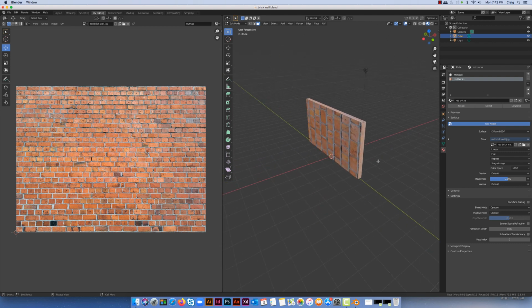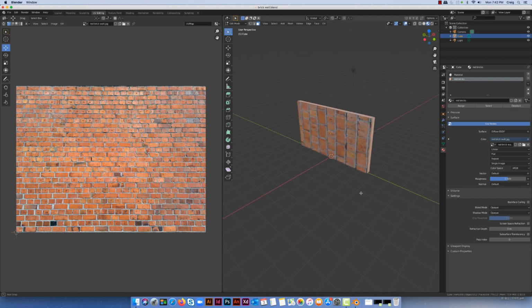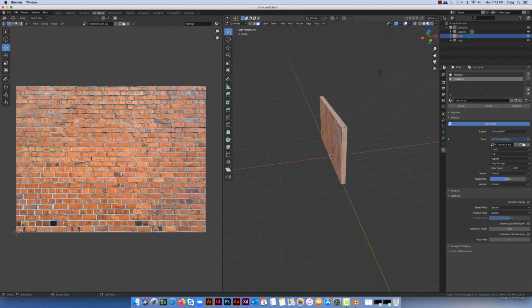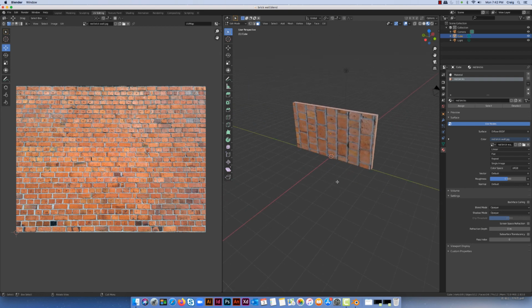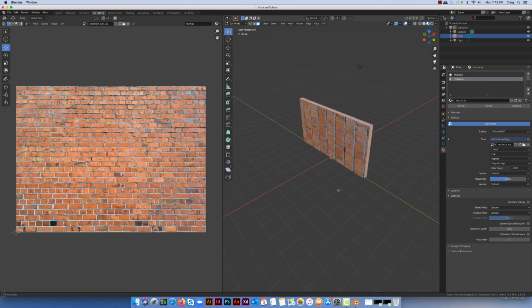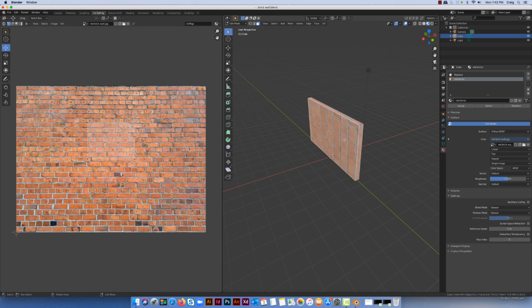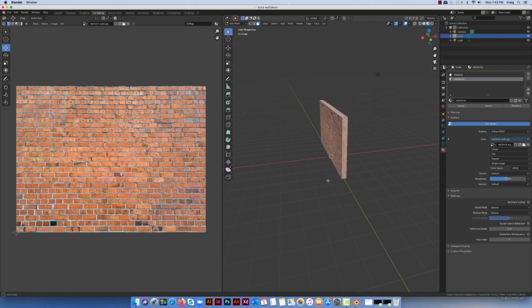If we look at the back, because I haven't unwrapped the UV yet, it's still kind of on that default setting, and even these edges along the side and the top, I need to fix those as well. So I'll just go through the process again. I'm going to select the face. You can see this is the face here. I'm going to right click and I'm going to unwrap it, which automatically positions my bricks in the right way, and just use my move tool to position the vertex in the right place. And that will give me a good looking brick wall down here.